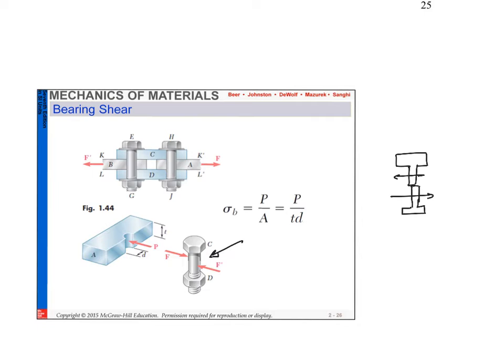Now imagine that the bolt was very, very strong, and it leads to a compression force on this area of the plate that would deform the area in front of it. Is this possible? Yes. So in other words, if I'm pulling on this sheet here, and my bolt is very, very strong, I will end up cracking the metal itself. How do I calculate the stress that is applied on this part of my metal? This is called the bearing stress.